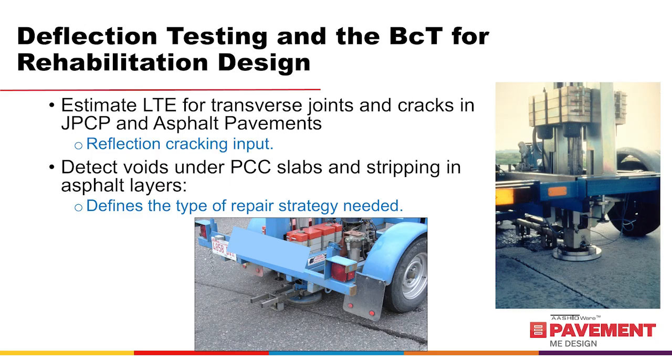Deflection basins are also used to detect if there are any voids or a loss of support under PCC slabs and estimate whether there could be severe moisture damage or mixture disintegration in the asphalt layer to determine the type of repair strategy needed for the project.